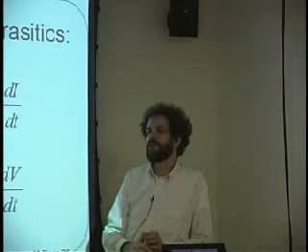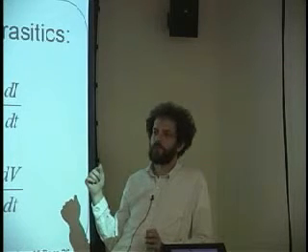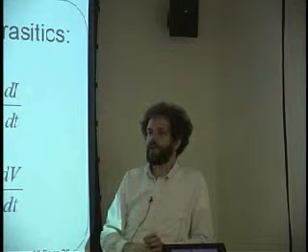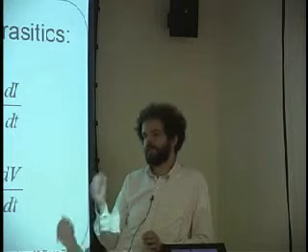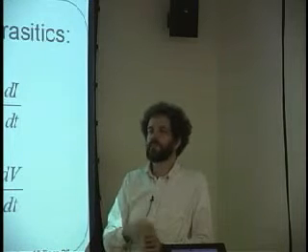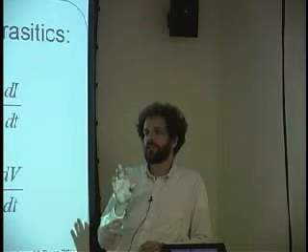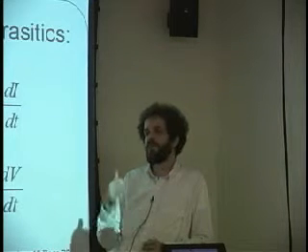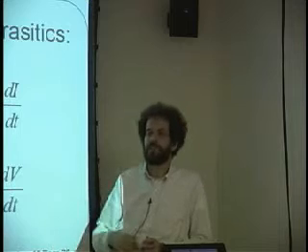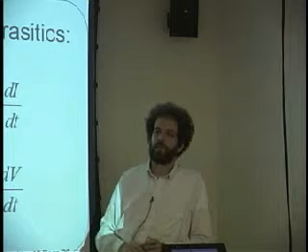But for certain modes of signaling where you're applying a DC current going down the wire, then I believe you're right, that the speed of the charge carriers going down the wire is the same as the speed of the bit that's going down saying there is current. Okay, but that's not the usual case. It's usually more like this. You're going up and down. So there the answer is no, that the carriers don't actually drift towards the end. But they change like this on this end, and that change propagates towards the other side.